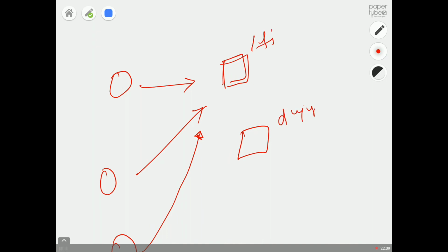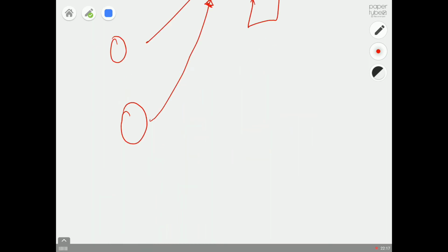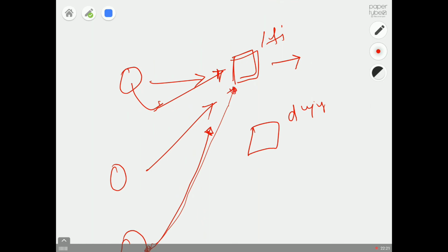So you finish reaction 1, you use the filtration unit, take the filtered product out, clean the filter, and then if you have some time interval, you take the product from unit 3, filter it here, and so on. That's how process scheduling works. It's not complex, but you need to know what you are doing, you need to know the time involved in everything.